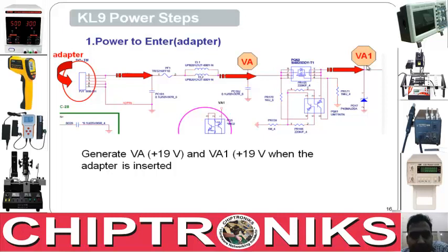As I have explained in my MOSFET chapter, we can replace this MOSFET. The question arises, can't we replace this MOSFET by a diode? No, we can't replace a MOSFET with a diode, because across a diode you have a voltage drop of 0.5 to 0.6 volt, but across a MOSFET the voltage drop is negligible. And we cannot afford to have any reduction in voltages in a notebook motherboard. You can call this a law of notebook motherboards.